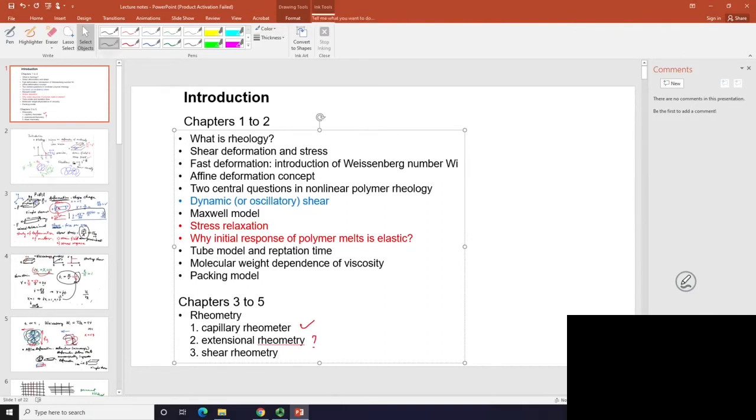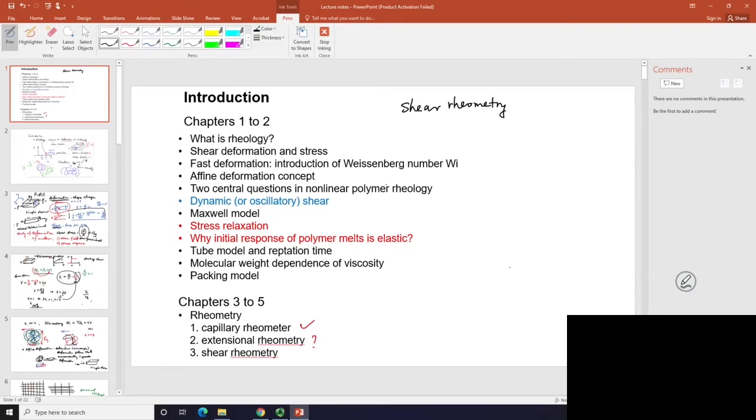This shear rheometry has a lot of challenges, actually. So perhaps it's wrong for me to omit it. But rheometry of shear, the simplest one is what we already did. Parallel plate like this, and you start to move one of the plates to the right, either some speed or certain magnitude, depending on what you do.